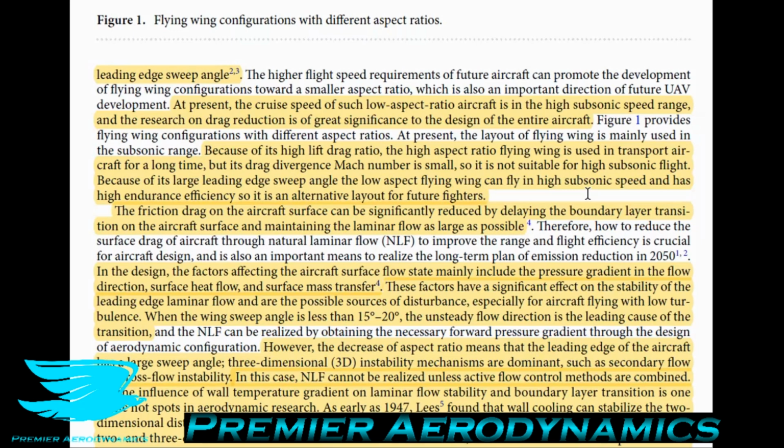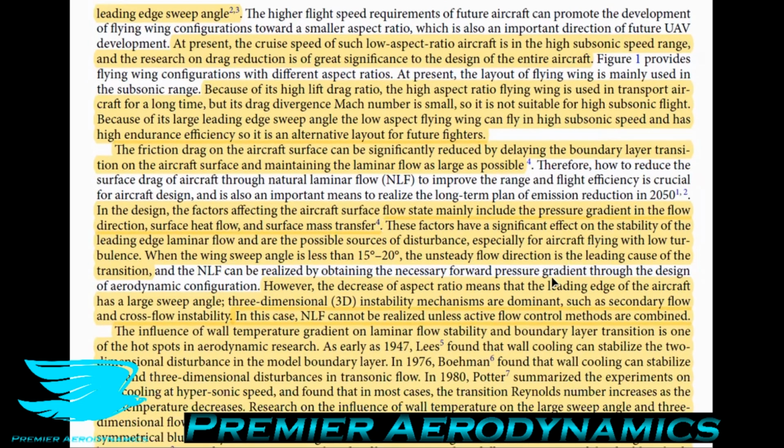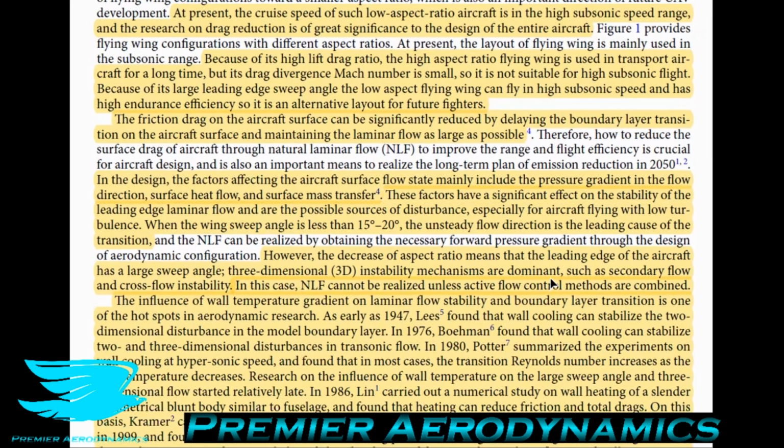If you have a very small disturbance, the viscous effects of the flow will dampen that out and you won't get transition to turbulence. So that's why they're talking about this here, in terms of how these different factors can greatly influence the boundary layer transition point in flows where there are very low turbulence levels.